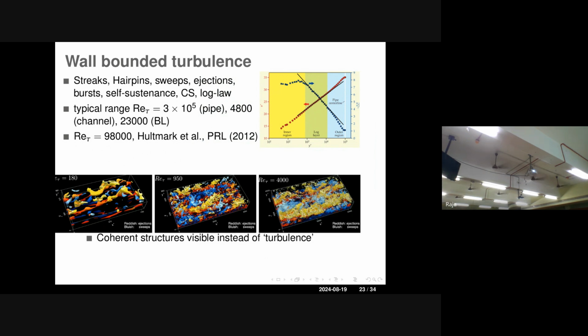In these turbulent boundary layers, there is always a mean flow. If I am looking in these logarithmic regions, are there any zones of flow which go much faster than the mean flow at the local level? Are there any layers which go a bit slower in velocity compared to the mean flow at the local level? They create some kind of twisting motions there, creating more stresses in the system. So understanding the structures always helps us understand how this drag really acts on the system.